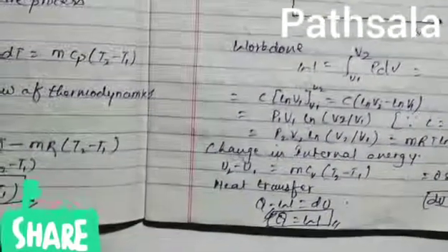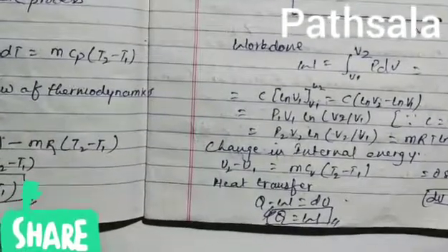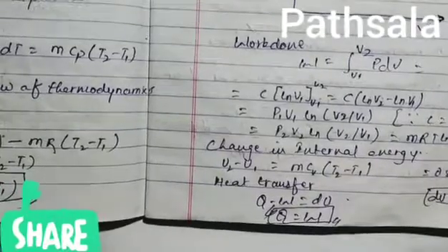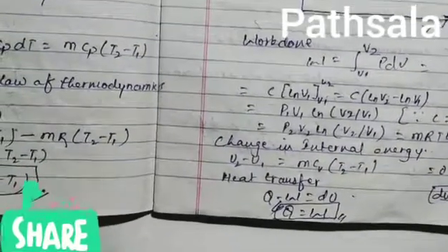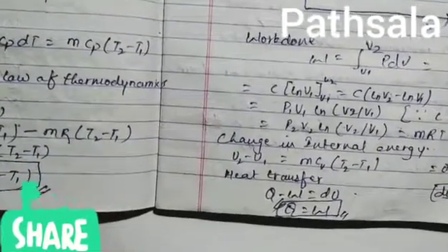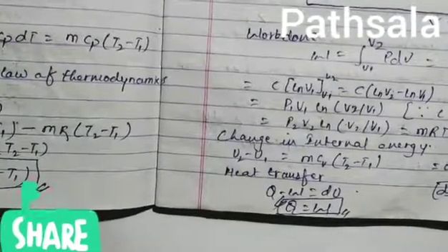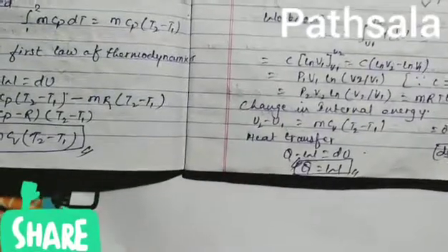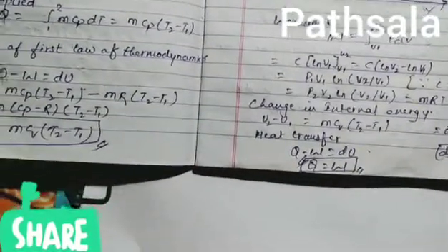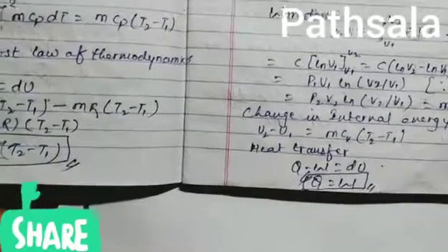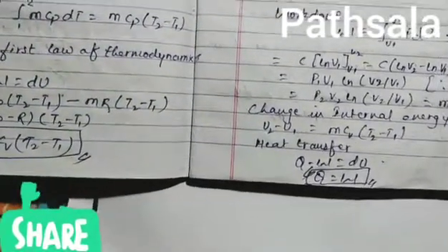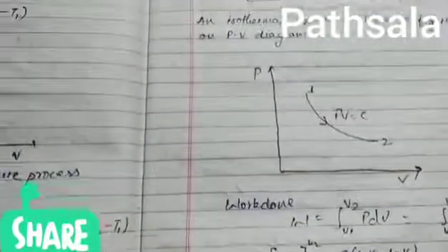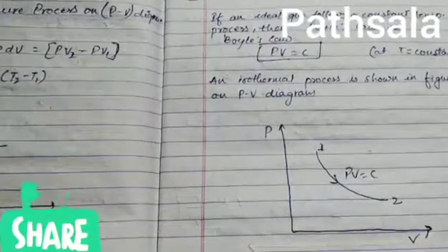Now the change in internal energy, U2 minus U1, is equal to m Cv delta T, that is T2 minus T1. Here T2 is equal to T1, so dU, the change in internal energy, is equal to 0. So the heat supply is equal to work done, that is P1 V1 ln (V2 upon V1). This is the final result in the constant temperature or isothermal process.